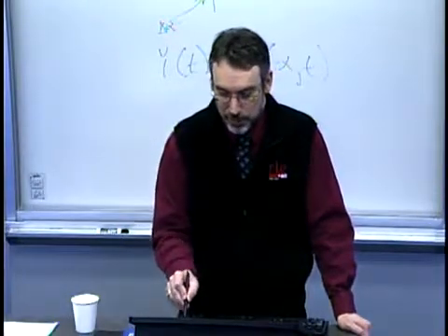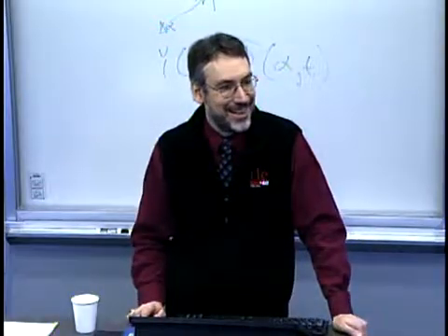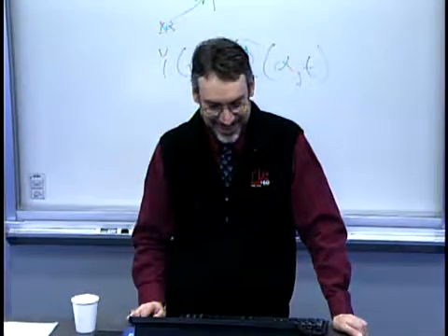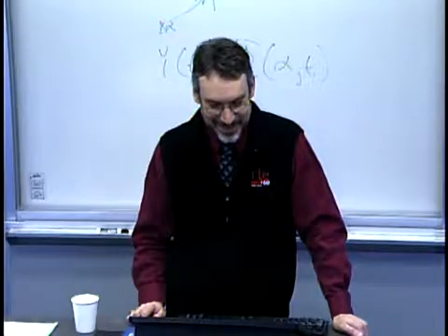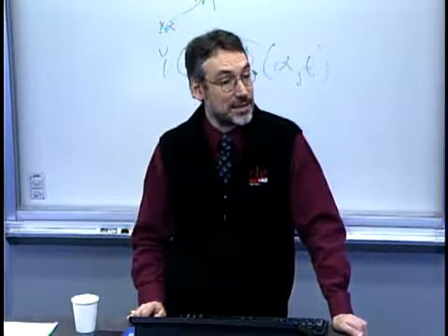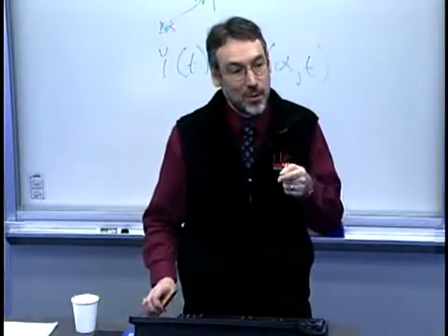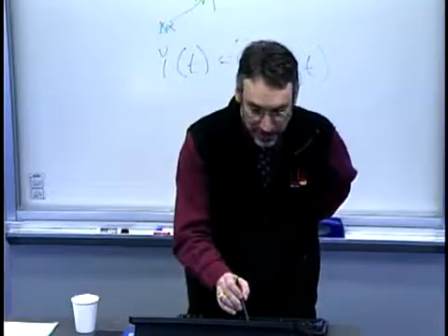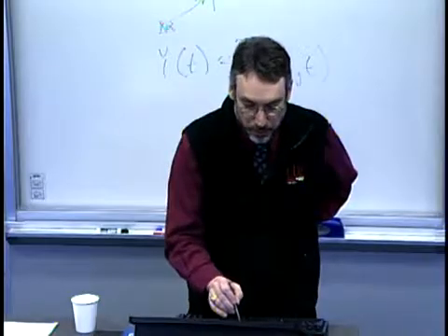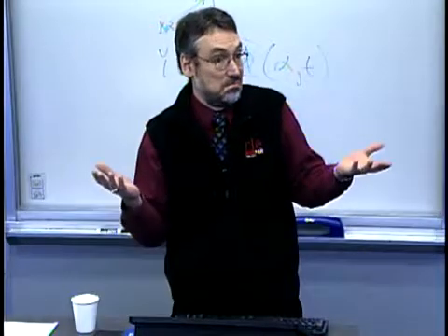Yeah. Good. Yep. I won't agree so much on the control part because in the first shift he is more consistent. I mean, all the outer dimensions are larger than the lower ones. And in the second shift, it's all dimensions. Interesting. Yeah, so it's a situation here where we don't know the specifications. So it's a little hard to actually know which is better. Because your point you were making is, in this case, the blue's always above, or almost always above the purple, always above the yellow. And it may well be that it's meant to have a slight taper to it. We'd need to know more.